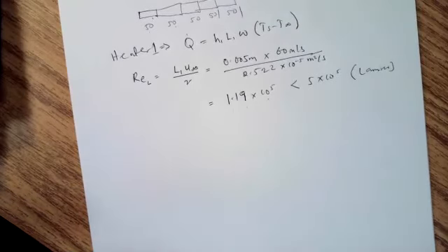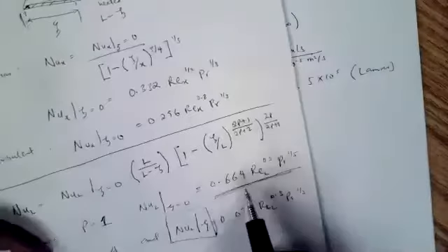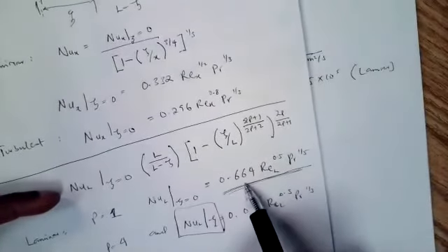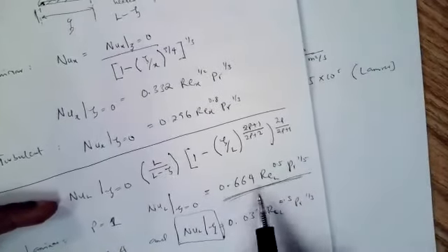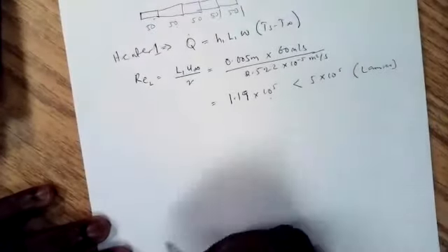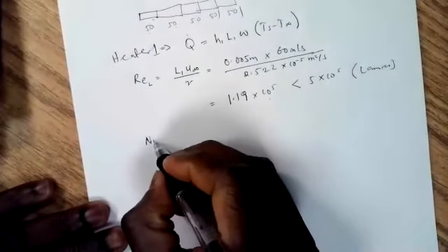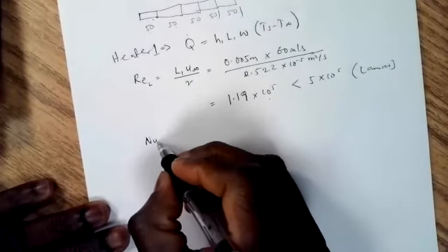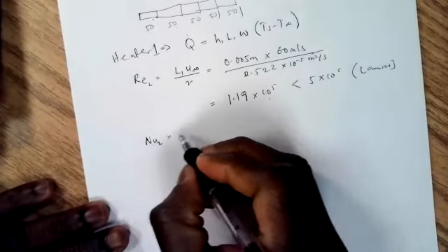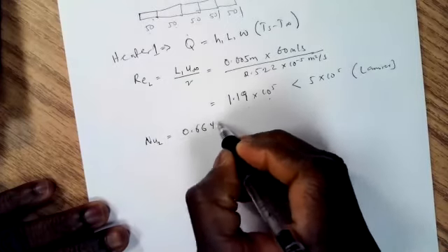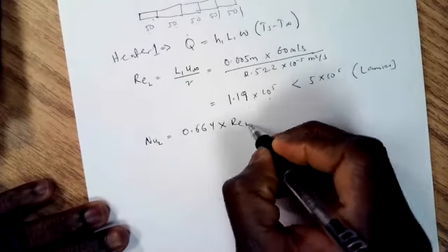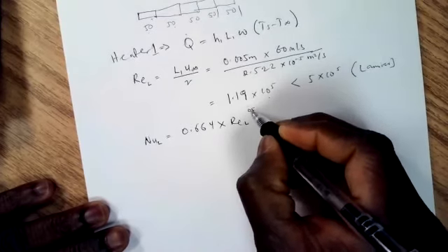So it is a uniformly heated plate, laminar flow, and we already established the formula for that kind of system, which is 0.664. That's the formula we're going to use. So we'll find the Nusselt number using that formula, which is 0.664 multiplied by 65.